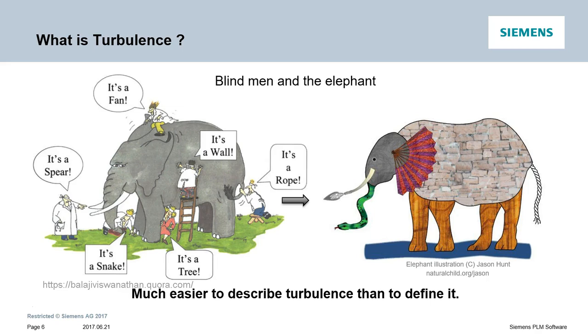Nevertheless, this concerted effort has helped us build a reasonable picture of turbulence. We understand what causes turbulence, and we can easily recognize it when we see it. So what causes turbulence? Turbulence is a manifestation of fluid's reluctance to flow along smooth and steady path when exposed to shear while flowing at modestly high speeds. High speeds means my flow is convection dominated and viscous damping is too weak to kill any fluctuations, which can eventually grow to turbulence.